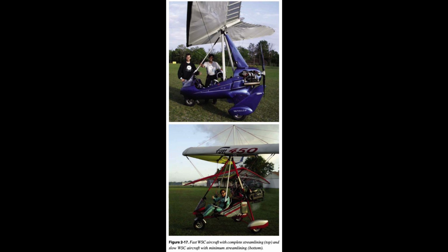Figure 2.17. Total drag is the combination of parasite and induced drag. Total drag equals parasitic drag plus induced drag. To help explain the force of drag, the mathematical equation D = CD x Q x S is used. The formula for drag is the same as the formula for lift, except the CD is used instead of the CL.